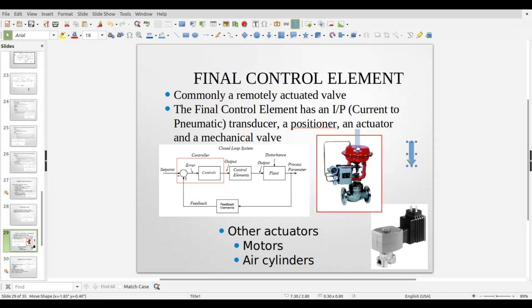We're going to send this 4 to 20 milliamp signal into the electrical box of this valve. And then it's going to use that to decide how far it opens or closes the flow valve to allow things to move through it.